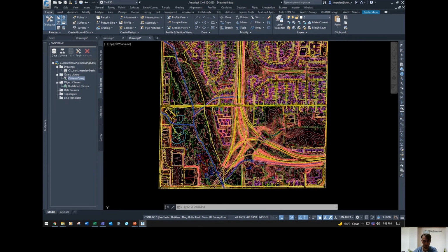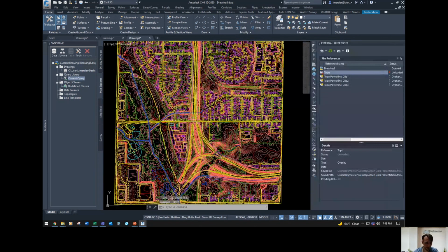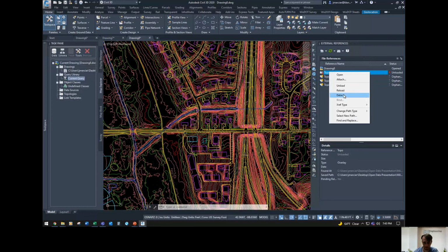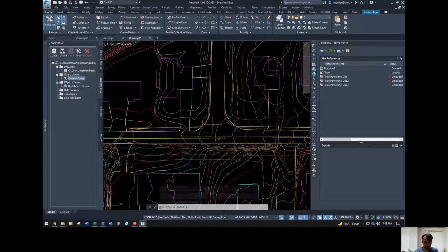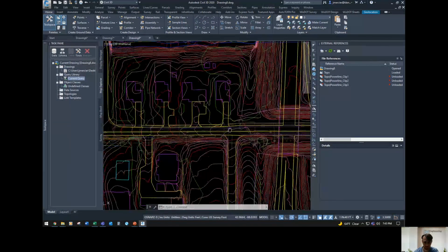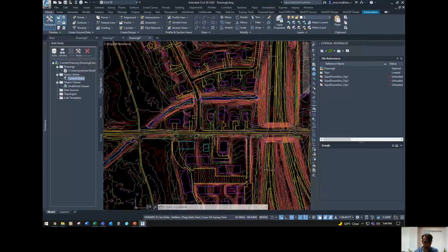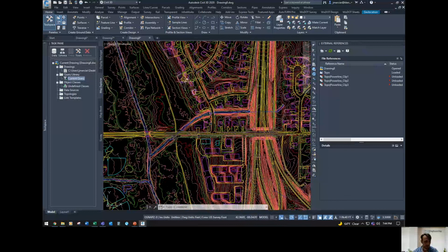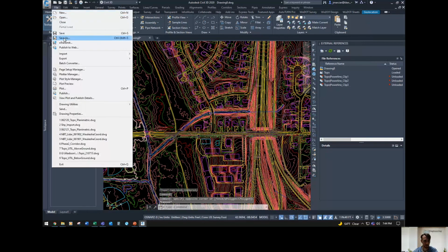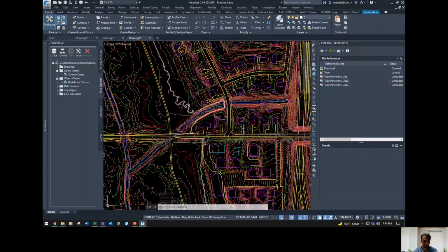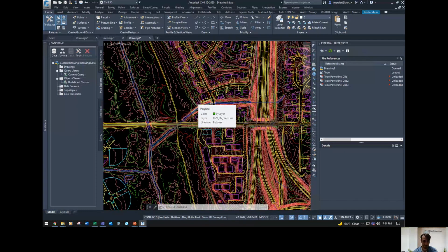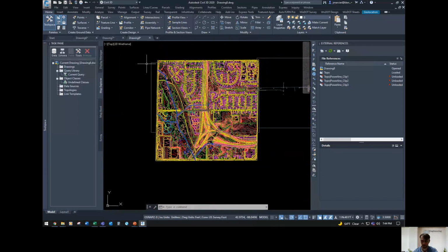And then we brought in the topo file of our survey just to make sure that it is in the proper coordinate system. We'll load that up here. And you can see that our survey does match up pretty well with the actual edge lines and whatnot that are provided by the county. So the last thing we would do here prior to saving this drawing would be to detach the old one, and then you can do a save as wherever you want to keep this information. Eventually, I would probably break this out, get the contours out of this if you want to use the other information elsewhere, just to make it a more simple drawing to use.